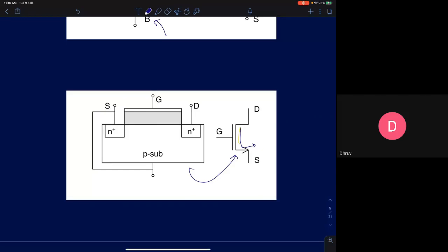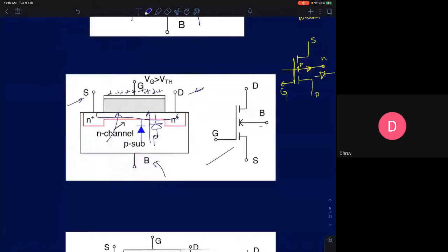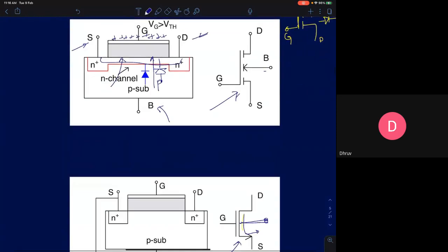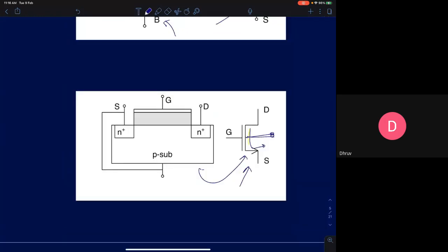In the software Cadence which you are using, they'll directly show a 4th terminal this way. But this is the history of symbols. So if you are going to show it as a symbol, this is how we'll show it, to show the bulk as a 4th terminal, or we might directly give you this one. Here it's assumed that source and bulk are tied together.